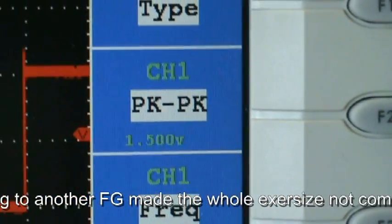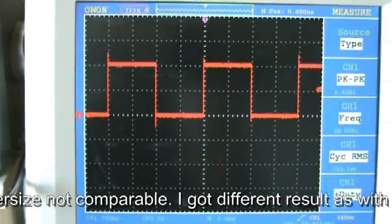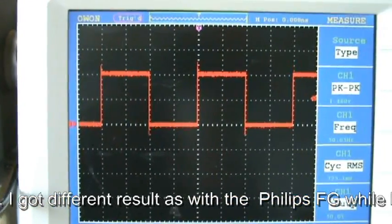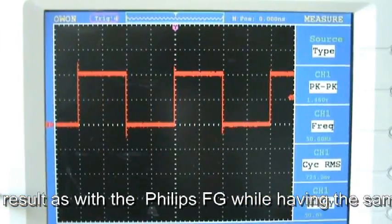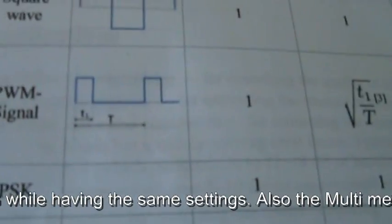It says 1.4, 1.5, but therefore I've put my scope to the half a volt per division, and I have a positive going pulse, 50% duty cycle at the moment, 1 volt positive. I use the offset of the function generator to get a positive signal, just like it has been seen here.